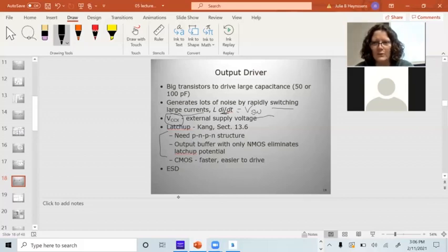So when we were told that we were just blowing the little devices because we didn't know how to handle ESD, if you could have seen the steam coming out of my ears. But the lab has been completely outfitted. We've got ionizers, because the dry air actually produces its own charges, so it neutralizes the air around the devices. We have EOS protection. We have ESD protection. I've gone through the whole thing with a meter looking for static sources. I know there's no static up there.